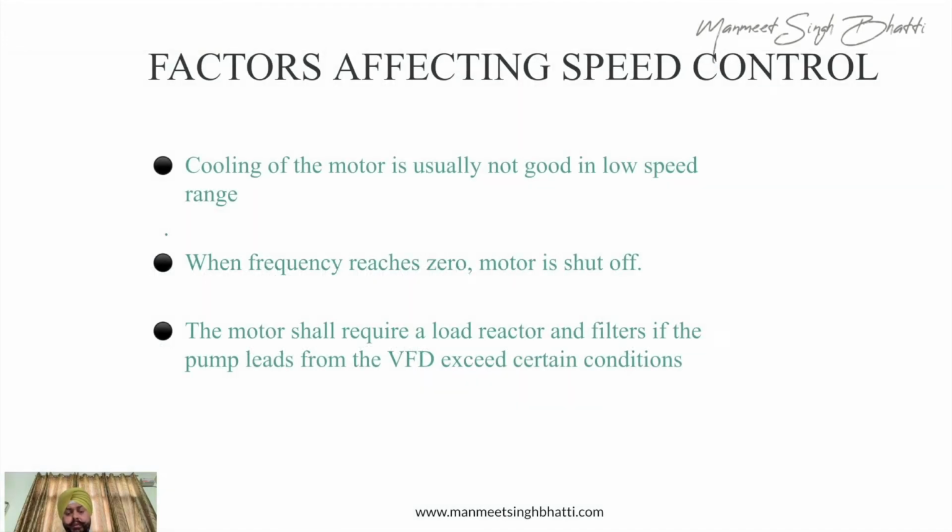Now these are a few of the effects you have to take into consideration when using a VFD. The VFD is a one-way controlling system, because it is going to give the power to that motor. But you must have seen mechanically that motors also have a self-cooling mechanism. There is a small fan on the backside of the motor, and that fan cools the motor, because motors also get heated up. So if you reduce the speed, the efficiency of that fan also goes down.